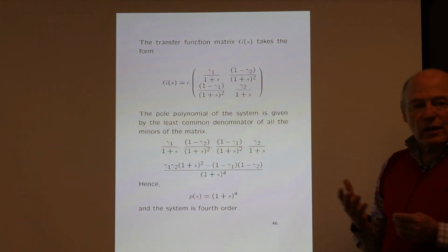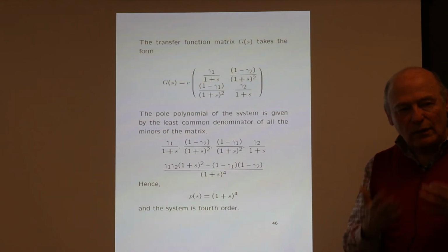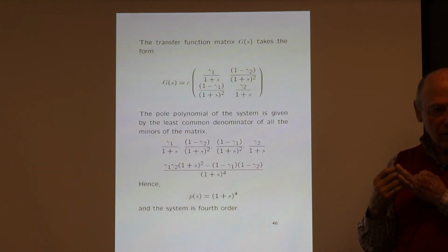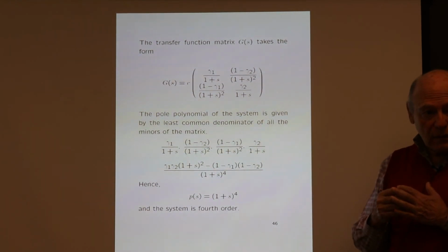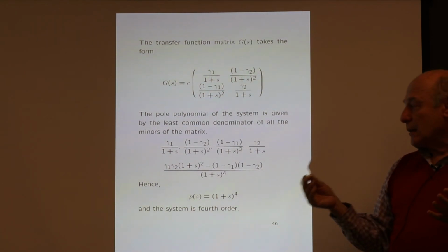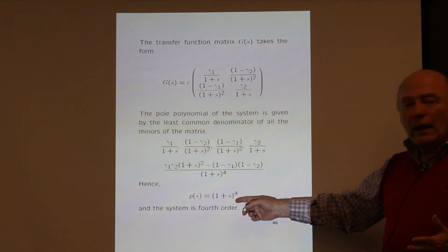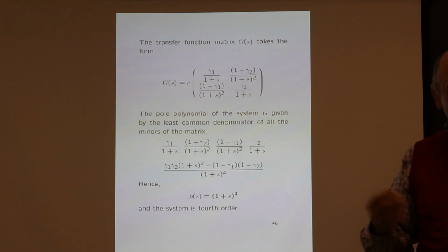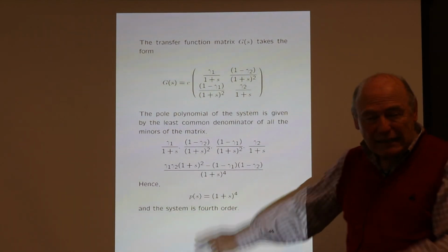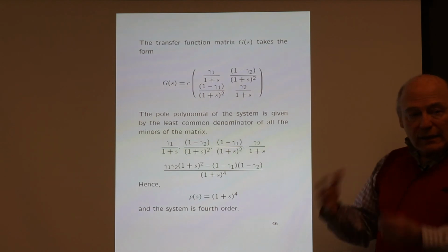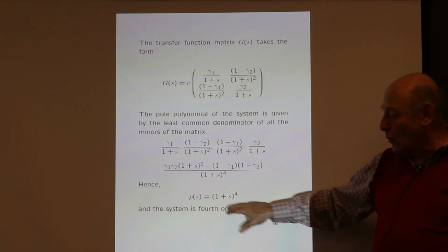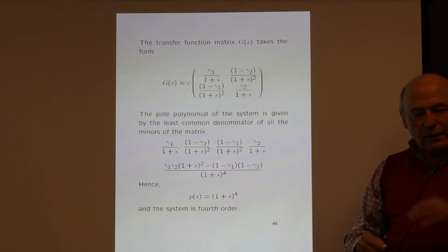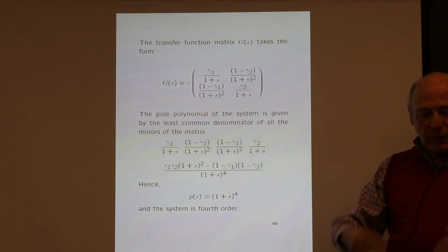Yeah, but that doesn't change the nature of the zero dynamics, which I'm interested in. We're looking at minimum and non-minimum phase systems. If I ignore the influence of gamma, I will not find anything. But here, of course, you're right. You will have four different parameters. But the most important case is the one in which you have more difficulties. Even though the tanks are exactly the same, their internal dynamics is not determined by the geometry of each tank. It's determined by the ratio of flows from the lower to the upper tanks.